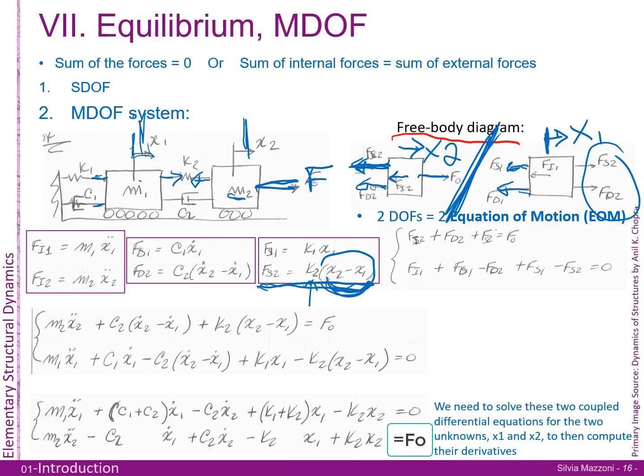If x1 minus x2, then that's going to give you forces that would act in this direction. So here you'll be plotting it this way, and then your signs would work out with that equilibrium. So it doesn't matter which way you choose. Sometimes I choose one, sometimes the other, as long as you then draw your force in the right direction. This is really important later on when you get into flexural members and look at things like shear and bending. It gets a little bit complicated, but if you deal with the right sign convention, then everything falls through properly. Okay? You're welcome to pause and go through this concept, but you can put it the other way, and then your forces will be in the opposite direction.